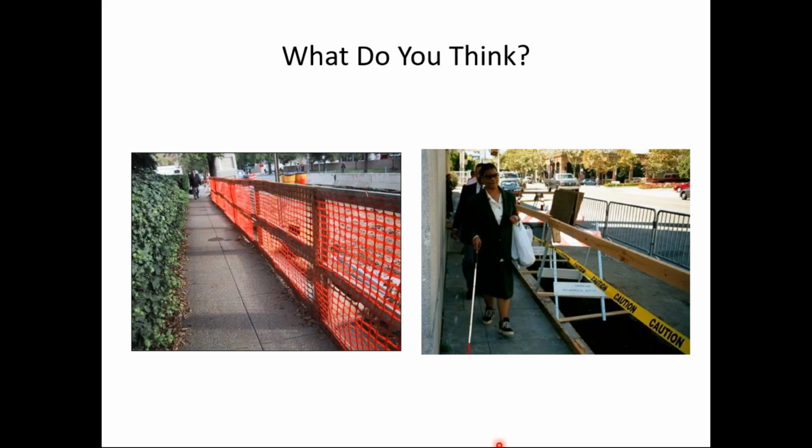Here are a couple illustrations. Let's start with the left side. I think someone last time asked about the netting, so I'll say a few words about that. But let's say this sidewalk, I haven't measured it, is 5 feet, so it's wide enough for an alternate path. Looks like they're just narrowing the sidewalk. I don't know the dimensions of this lumber here at the bottom, but let's assume it's 6 inches. If this is 6 inches or more, and it's firmly attached to the ground and to each other, I would say that meets the requirements of the detectable edging. If it's less than 6 inches, it does not. So for example, you couldn't use a 2x4 there because you're not going to have 6 inches vertically by just using a 2x4. Notice the netting here, this plastic netting.